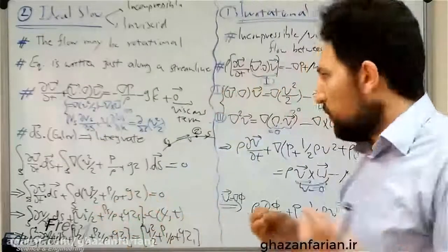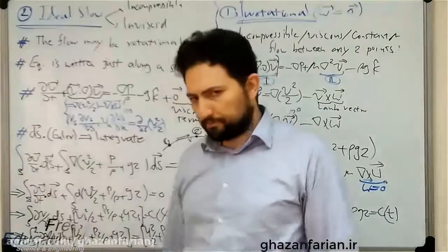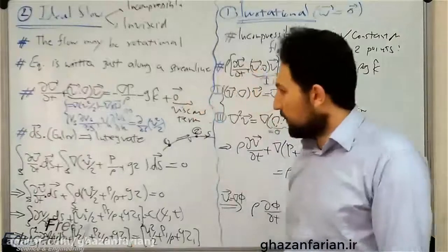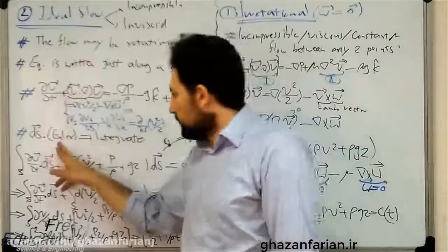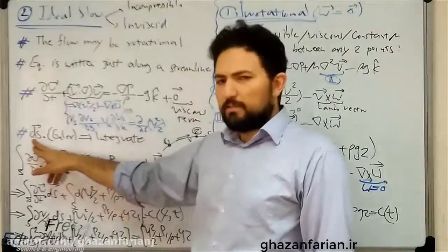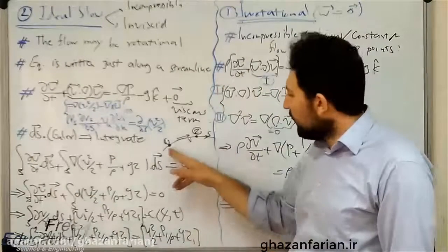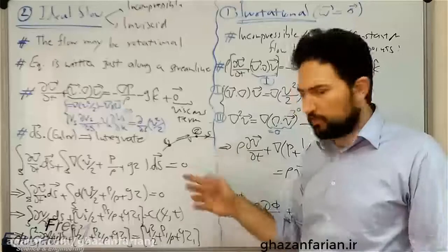So, you know that the dot product of two vectors is a scalar quantity. I want to compute the dot product of this vector equation, which is the Euler equation, and the ds vector. The s coordinate is a coordinate which is defined along the streamline. This is a streamline, an arbitrary streamline.